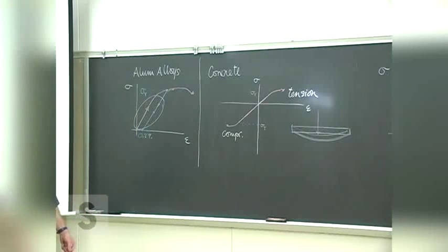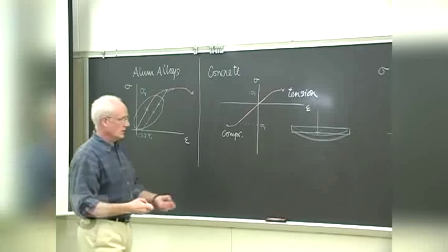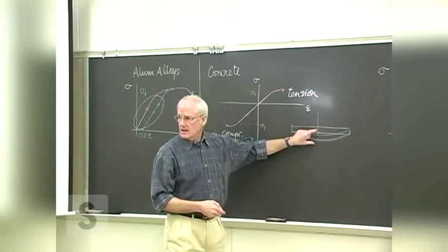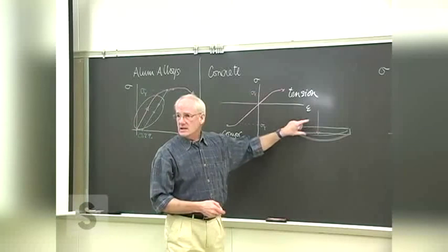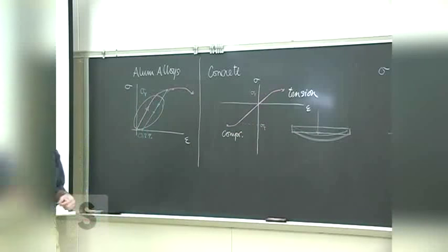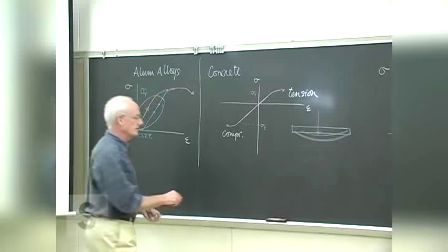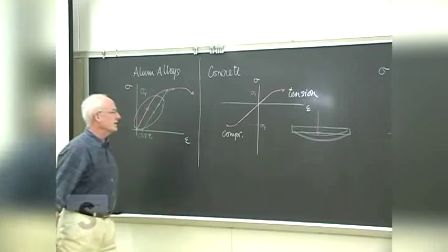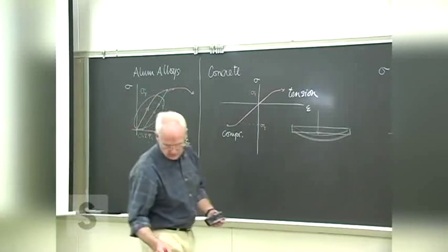But when we design it, as we look at this technique, we completely take the concrete in tension out of the calculation anyway, and assume that it's all on the rebar. Anyway, that's for the future, a little bit of a taste of what's to come.